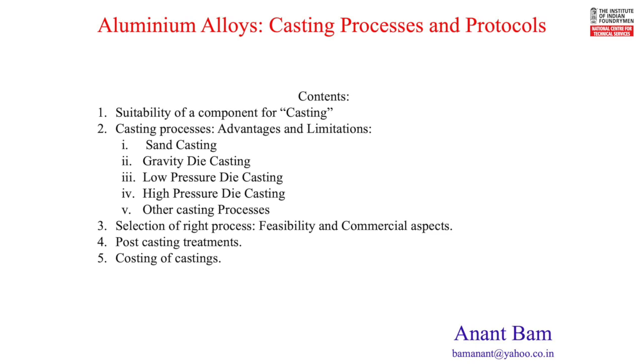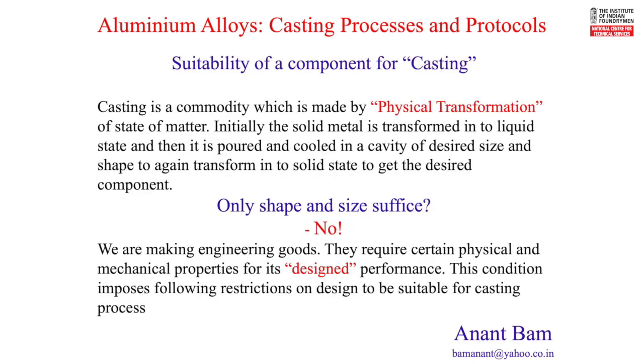During solidification, the grains of every casting are formed. All the physical and mechanical properties are directly proportional to fineness of grains. Too early solidification leads to chilling and delayed solidification leads to mushy structure. Both these cases are not desirable. This means we should have more or less uniform solidification or more or less uniform cross-section of the casting.